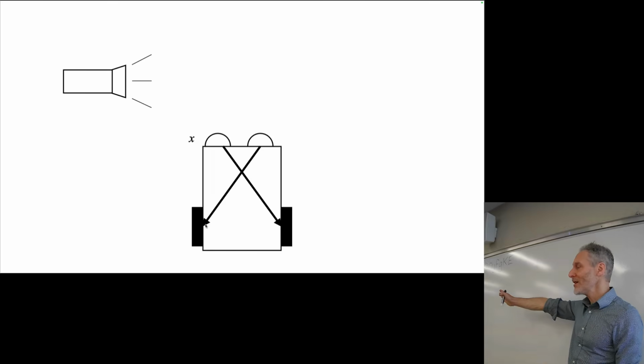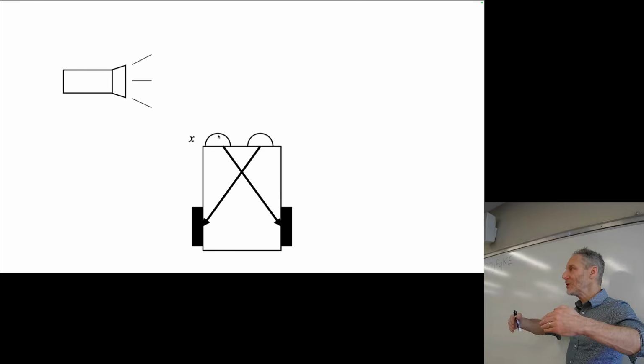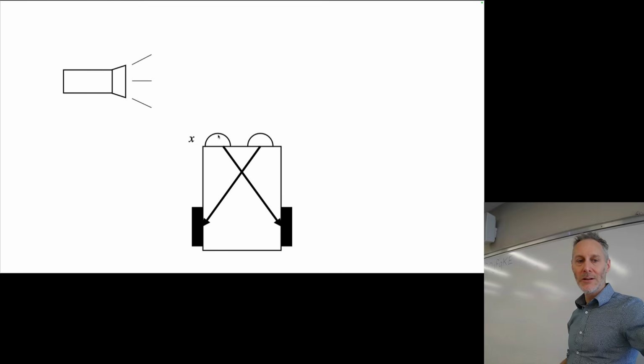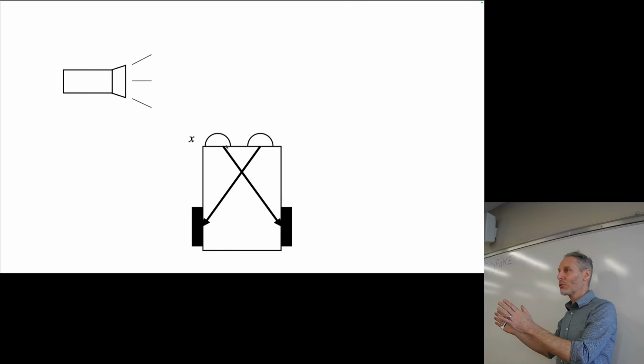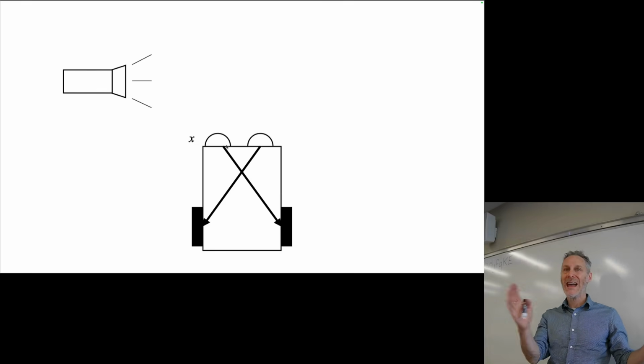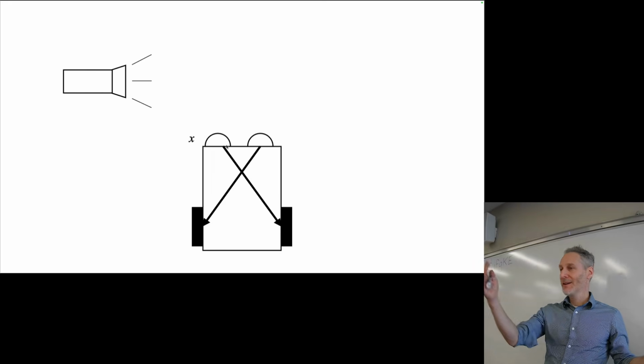Remember that in theory, this all sounds good, but in reality, these sensors have a refresh rate. They can take a value, and then a 60th of a second later, they can take another value. It's possible, under certain conditions, that the robot would turn too much, and now what's the situation once it's turned past the light? Now what's happening? Now it's got to swing back and jitter towards it.